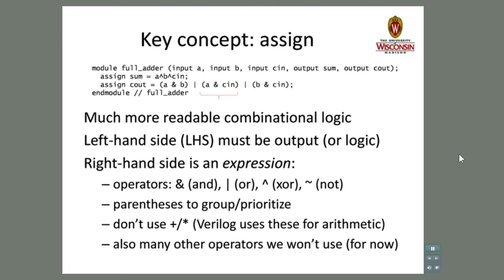This example of a full adder illustrates how much more concise and readable assign statements are when compared to the gate-level structures shown on the previous slide. As a final note, keep in mind that even though assign expressions look a lot like assignments in common high-level programming languages, they are not the same thing. They are converted into gates and nets and evaluate constantly, unlike assignments in programs, which evaluate only when the program executes them. Hardware descriptions, even though they look similar to high-level language programs, are not software.